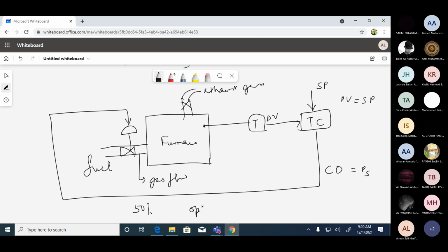So this is called the optimal response. Optimal response means the controller will take a decision to allow the valve to remain open so that this condition is satisfied. And that is why we always need to have a constant output. If you don't have this constant, your valve will close or your valve will become fully open. There is no in-between position. So usually we allow the constant output to be about 50% so that the valve can be half open.